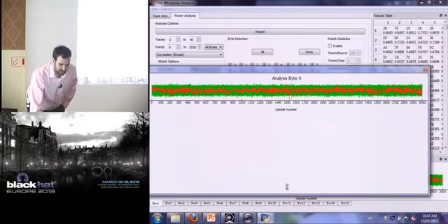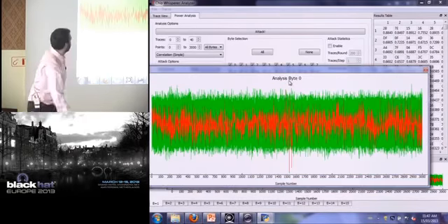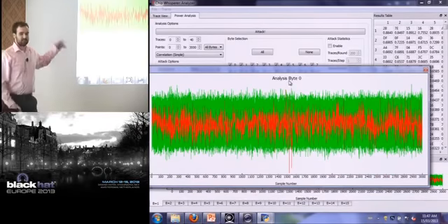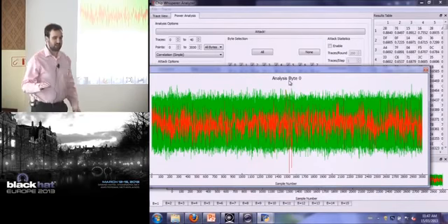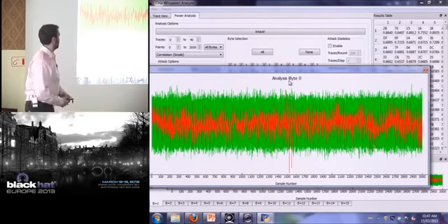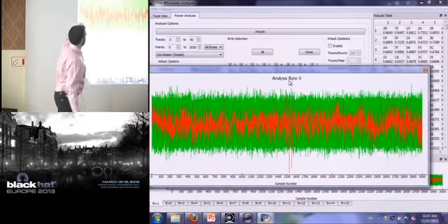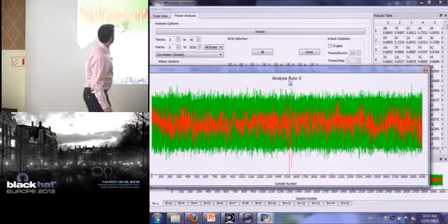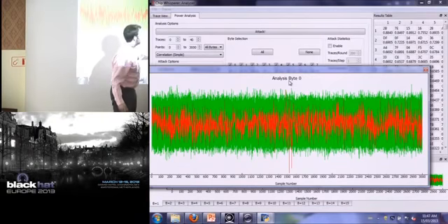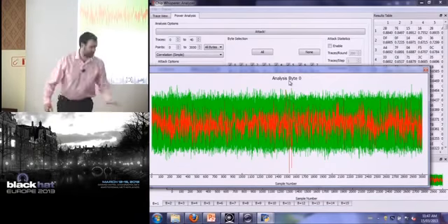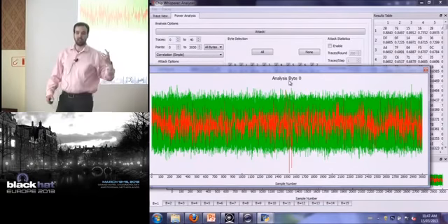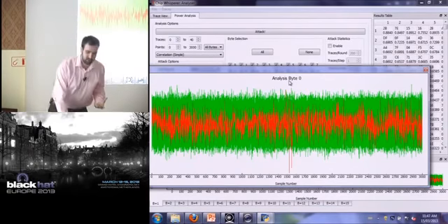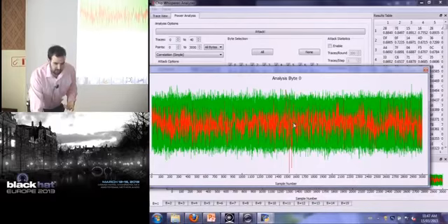This is showing you, for byte 0, the correlation between all possible key guesses. So it's plotting 256 possible key guesses. And in red, it's highlighted the one that I know to be correct ahead of time, because I know what this key is initially. And what we can see is that the red trace at one point all of a sudden has much higher correlation. So this is telling you right at this point in time, this is where that operation actually occurred. So this is where the SBox lookup probably had occurred.